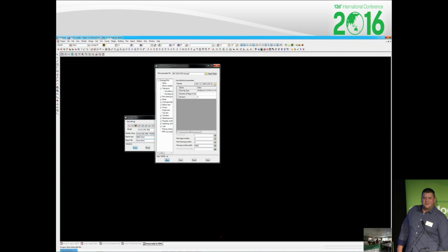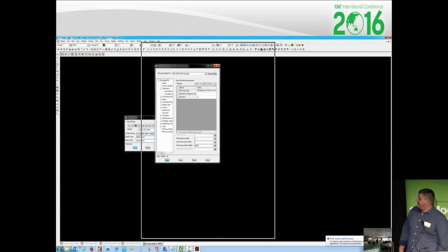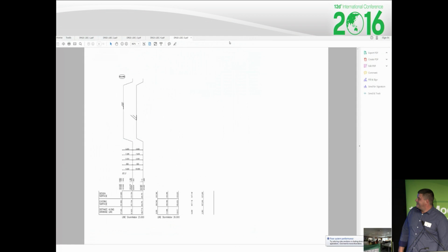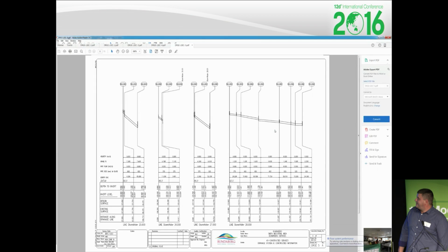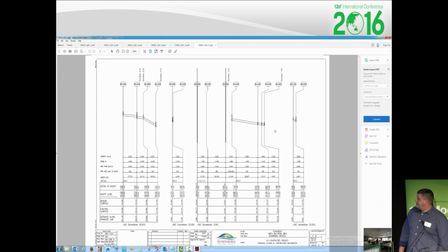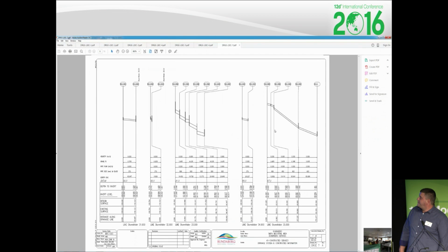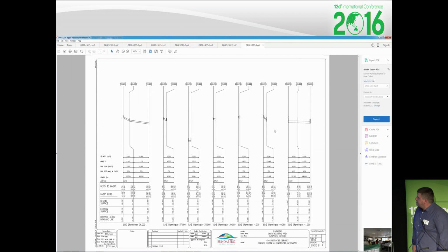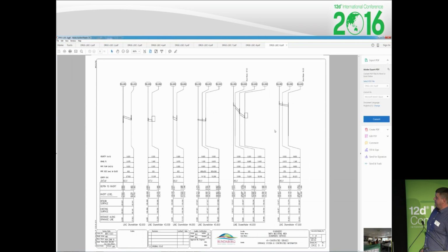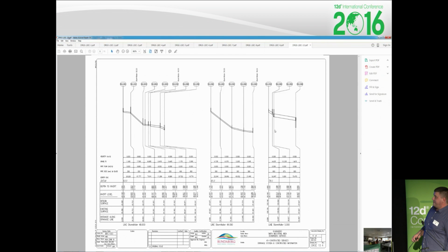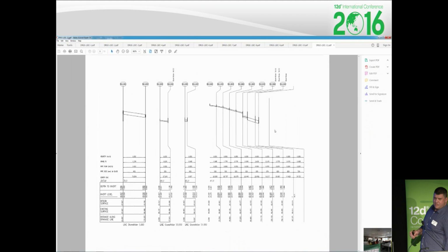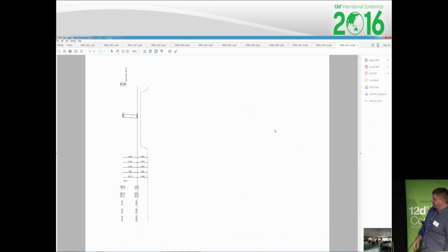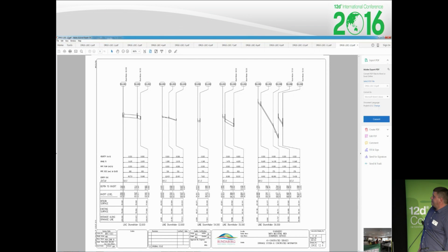Again, it's funny, it feels like a long time here, but it's only really been about 10 seconds. And that's our PDF of the drainage network in Childers. You can see a few manholes, you will see a few manholes shooting off into the sky. Again, that's because the default value being -999, so the calculations there send that surface off the page.